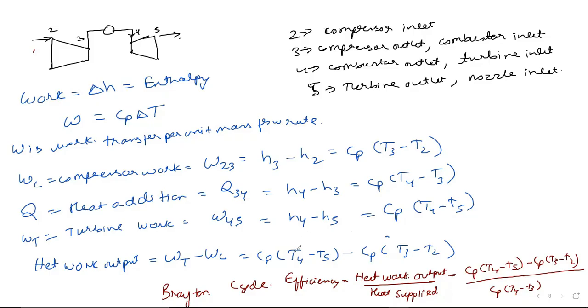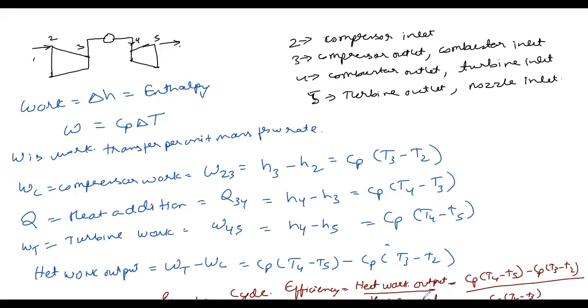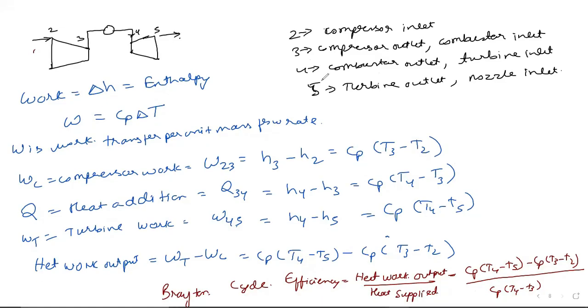But velocity will be there. In compression we will see the velocity triangle, and in the turbine we will see the velocity triangle. So you must join tomorrow's class because we will be starting the jet engine analysis. In it, we will discuss types of engines, then pressure ratios, temperature ratios, some simple terms. Suppose pressure ratio, P3 by P2, which is known as small r. It is the pressure ratio across the compressor, and we will discuss how efficiency and temperature ratio change across the compressor.